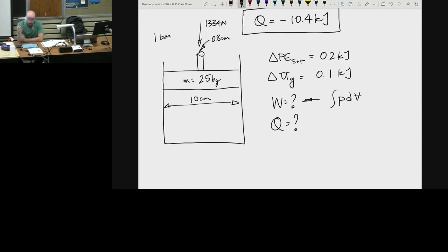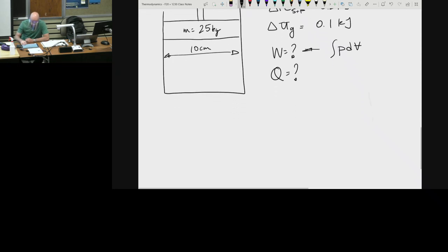So we go back and read our problem statement, and ask if there is anything that says it's polytropic. It doesn't. It doesn't say n is equal to something, it doesn't say PV^n is equal to something. So we're going to assume that pressure is constant. The other thing they say in the problem statement is that the friction between the piston and the cylinder is negligible. It's really smooth movement up and down. So we're going to assume constant pressure work. But we don't know the pressure inside that piston, and we don't know how far it goes, what the volume is. So let's find that out.